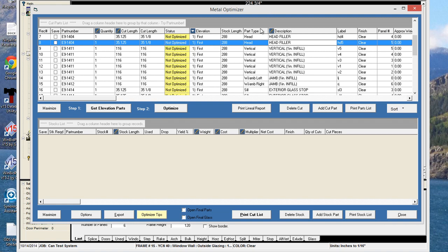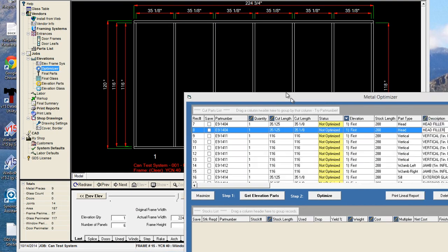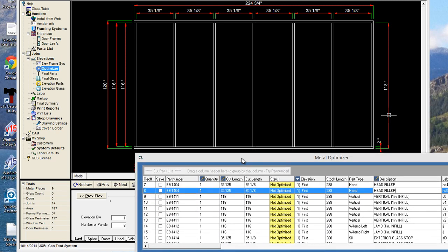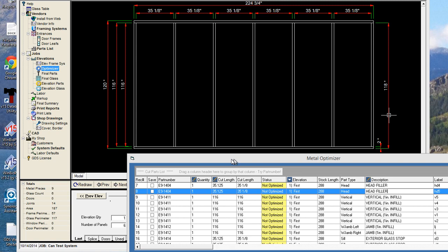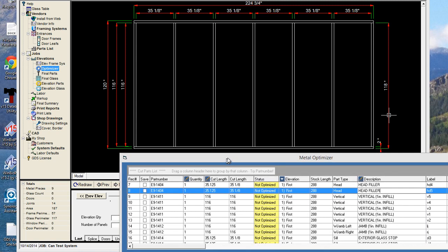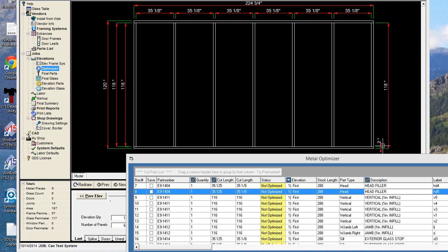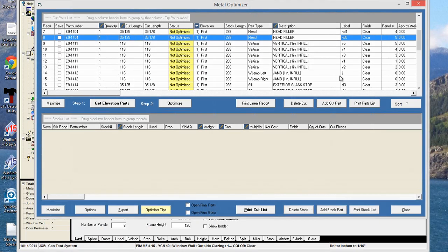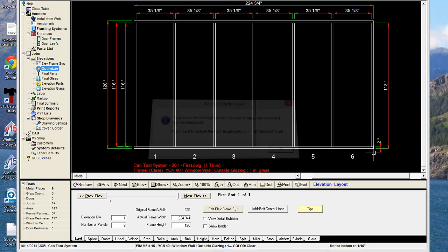Where's our vertical material? Here we go. Vertical and wall jambs at 116. I'm pretty sure that's what our dimensions showed, yes. So simply, that's why I like demonstrating with 2-inch systems, because they're easy numbers to work with. Nice whole numbers. And we see on the right here, we've got our 2-inch subsill or sill receptor, and obviously our 2-inch head can. So that's why we're getting the 116. So that's working out okay.